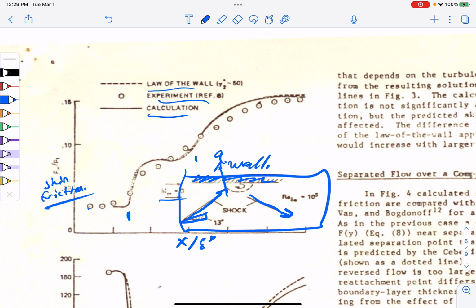And that's not computer limited, because today we have wall-modeled large eddy simulation. And when you hear wall-modeled large eddy simulation for these unsteady supercomputing simulations today, they're also assuming some form of the boundary layer near the wall. So you see this idea has stood the test of time. Let's look at another graph.